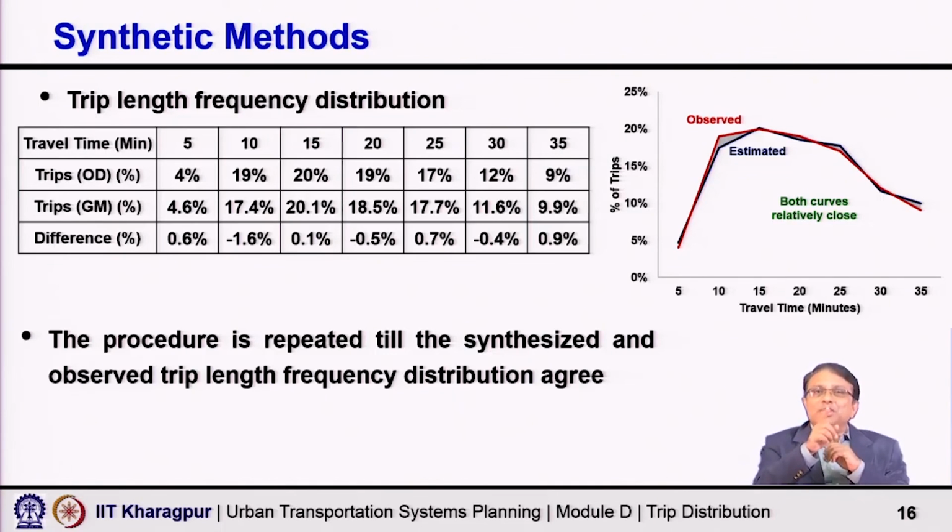So, now here you use the zone to zone adjustment factor or Sij value, which I used initially in the gravity model. Now you can use some factor to make some gross kind of adjustment and agreement for each and every cell within the total. So, the total is matching, now it is the zone to zone socioeconomic adjustment factor you can use to match those.